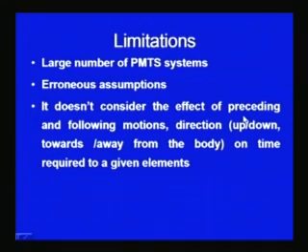So, the assumption that the time required for carrying out one particular job will be the same irrespective of the worker who will be doing the job is erroneous in this PTS system. It does not consider the effect of preceding and following motions and the directions on the time required for carrying out the job.